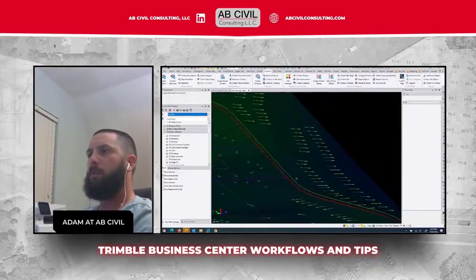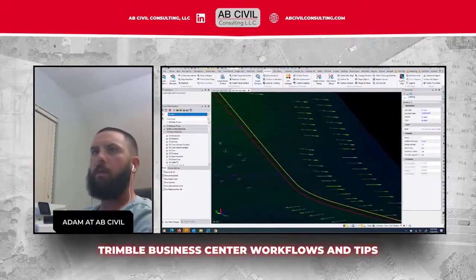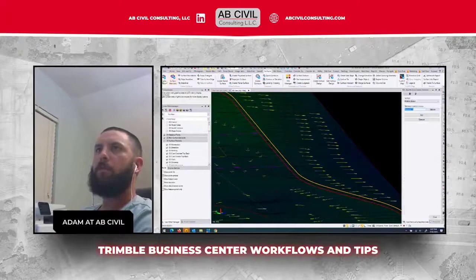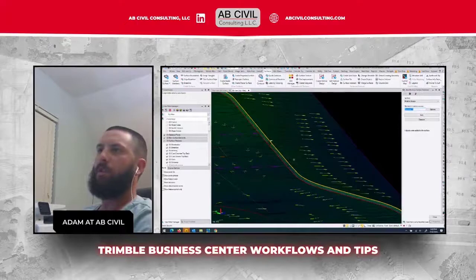So what I'm going to do is click on that line, not the surface, and make sure it's finish design. I'm going to go up here to the surfaces tab, surface members. I'm just going to hit add. It's going to add that line to the surface.